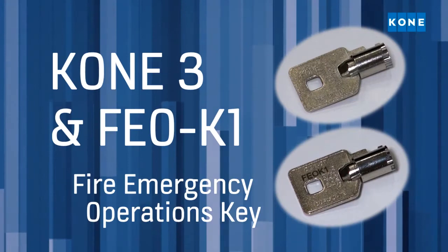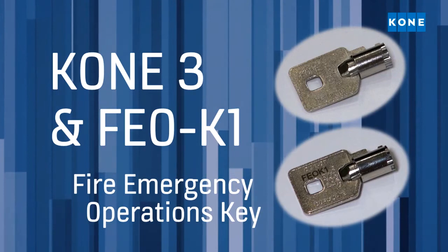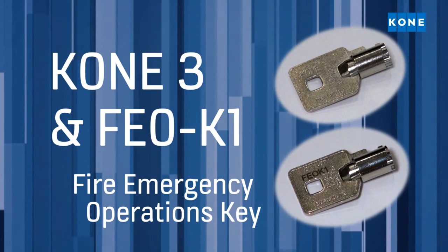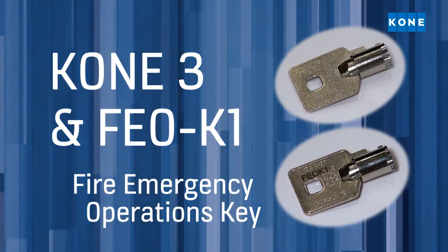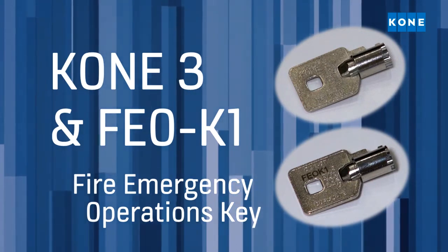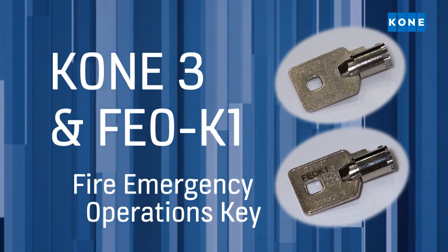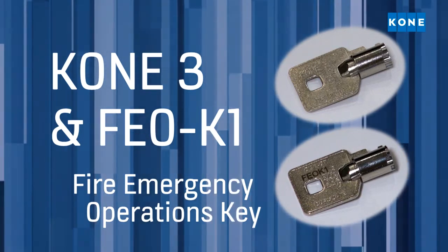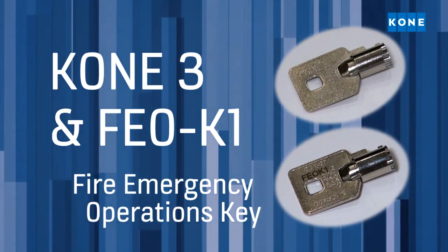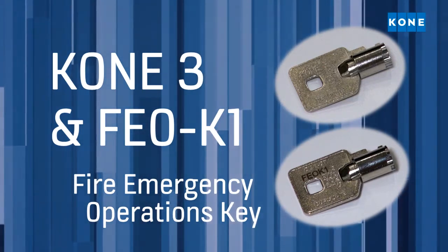Your KONE elevator is provided with a Fire Emergency Operations Key, as required by the ASME A17.1 and CSA B44 elevator safety codes. Your fire emergency operations key will typically be marked as FEO K1. Older keys may be labeled as KONE 3. Local codes vary as to how the fire service key must be labeled, with the FEO K1 label being the more recent requirement. Both the FEO K1 and KONE 3 keys perform the same fire emergency operations functions.